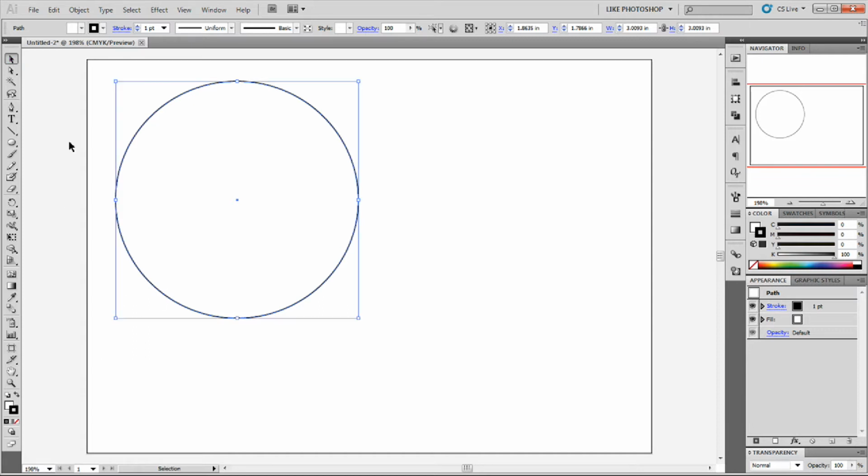And the laser cutter I'm using, the Trotec, the way it understands this file is it wants the stroke width to be the smallest, 0.25. I believe in CorelDRAW it's called hairline. In Adobe Illustrator it's 0.25. So I've got the right stroke width, and typically there's no fill. I'm going to take the fill out, and the outline or the stroke is red.